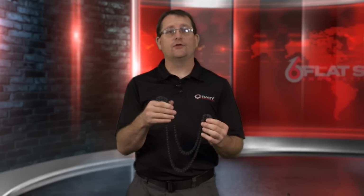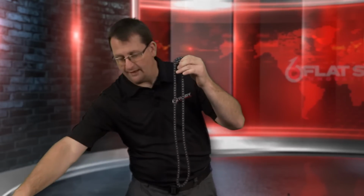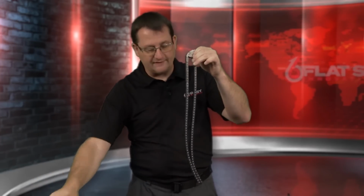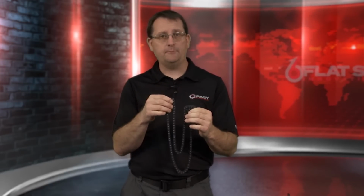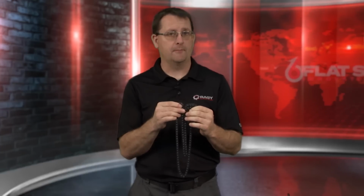A lot of times, with that being said, you can pop the sump plate off, like we show in our What's in Your Oil video, and it will show you some of the things that come from a timing chain that's stretching or wearing. It is going to shed ferromagnetic debris because, of course, this timing chain is magnetic. So you're going to end up losing that debris, and a lot of times it's very small, kind of a blackish material, and if you've got a magnetic drain plug, it will coat the surface of your magnetic drain plug.